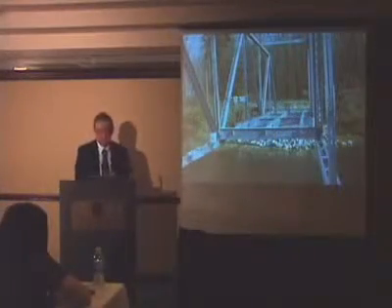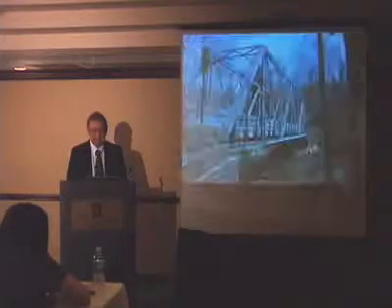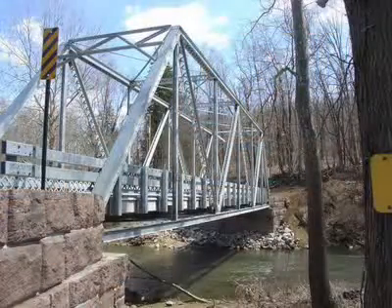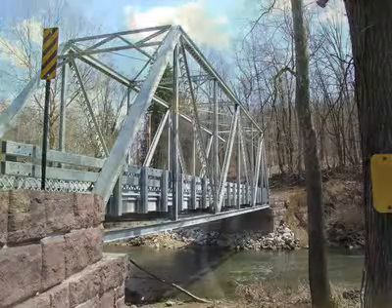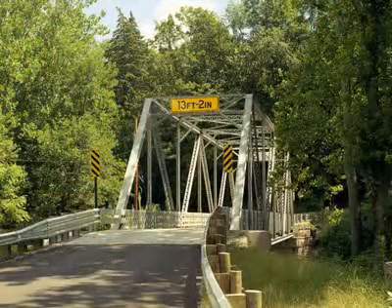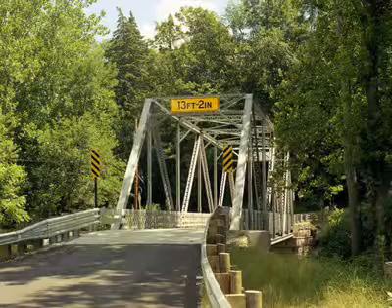It had shear studs that were attached prior to galvanizing. The completed bridge actually had a twin steel tube design, crash-tested railing, concrete deck. It was limited in height and width, but it carries the design for HS20 loading, like I say, with crash-tested railing and everything.